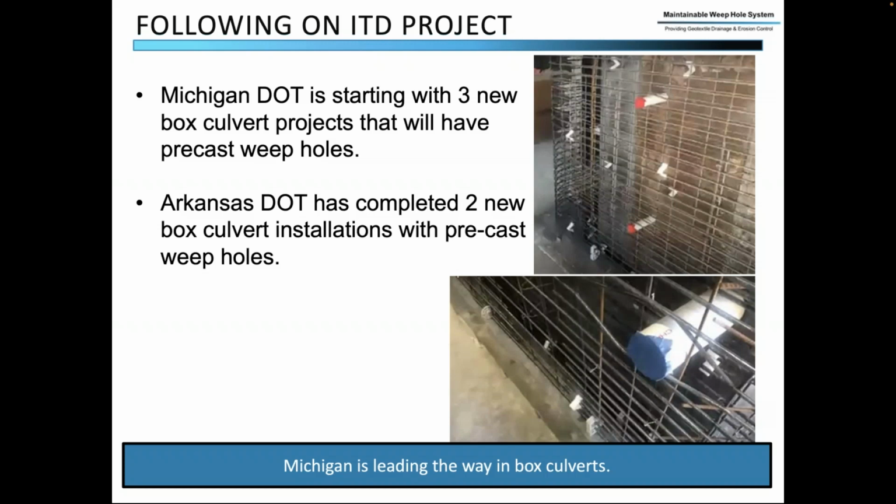The approach of the road dropped 8 inches. I'm not sure if this is from the trucks or just water coming out of the existing weep holes and bringing the soil with it. Their solution, just like MDOT had done at one time, is to use concrete and fill in the weep holes and hope that the wall lasts.